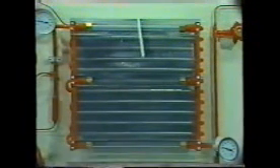Let's look at a small demonstrator of a vapor compression system to see how a direct expansion evaporator is constructed and how it actually works. These three glass tubes have been placed in the evaporator so you can see what's going on inside. This demonstrator shows only several tubes, but in a real system there may be many tubes, even hundreds in a single evaporator.